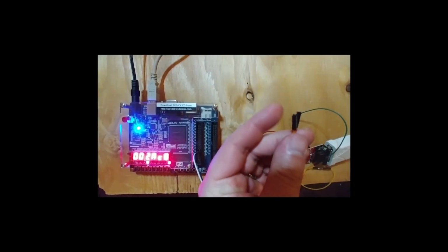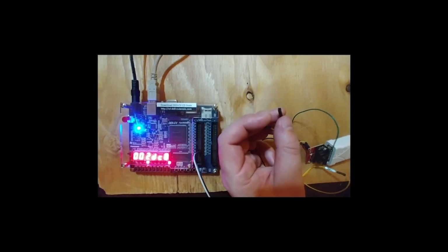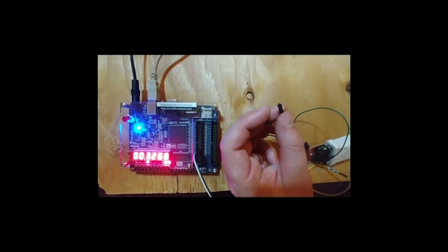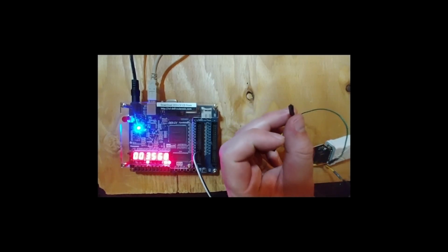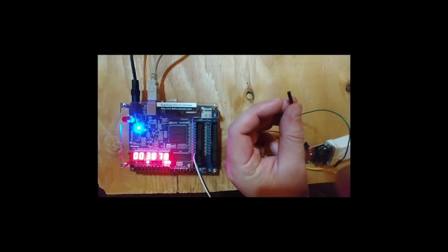Okay. And transmit was actually mapped to pin K19 on the FPGA, which is just below VCC, just below that white one. Except I'm not going to plug in transmit to transmit. I'm going to plug in transmit from here to receive over there, because that makes sense, right? This is transmitting to the receiver over there.